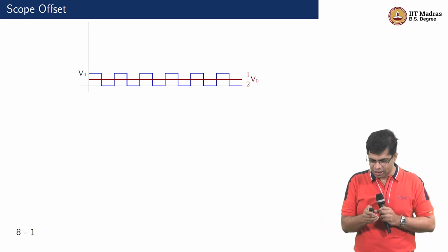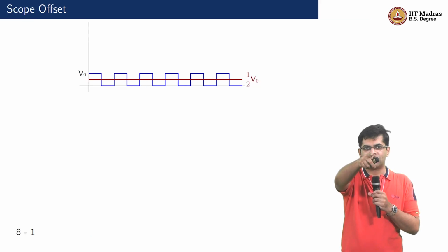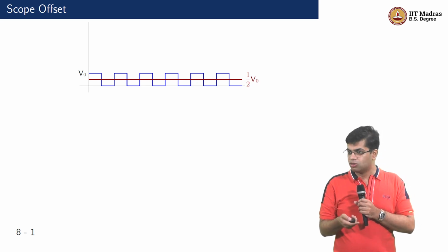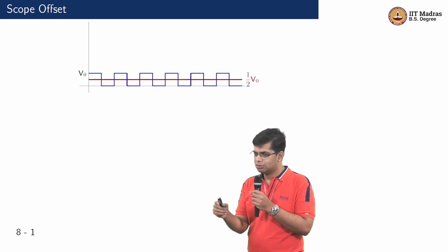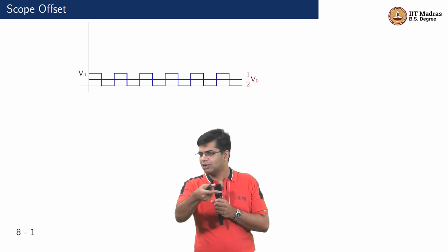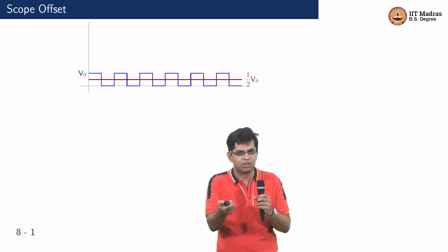Basically, what pulse width modulation means is I have a waveform whose duty cycle I can vary. So this is a waveform with 50% duty cycle, which is on for 50% of the time, off for 50% of the time. 0 to some voltage, maybe 5 volts, depending on the microcontroller, maybe 0 to 5, maybe 0 to 3.3, whatever. What if I take the average of this waveform? What will it give me? Half the value. Okay. So I have actually done D2A conversion. If I can change the duty cycle of the waveform and do averaging, I get an analog value corresponding to it. So that's what the pulse width modulation actually does.